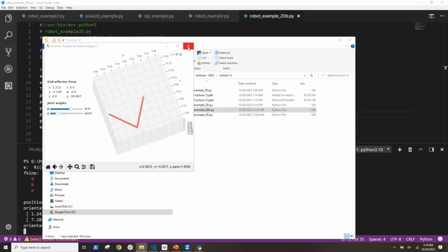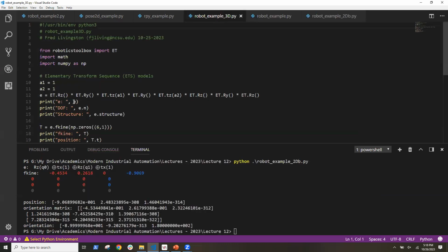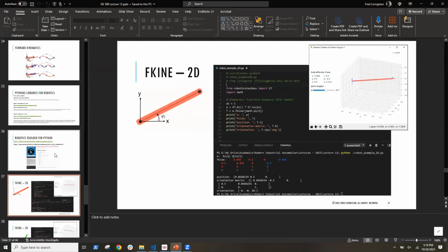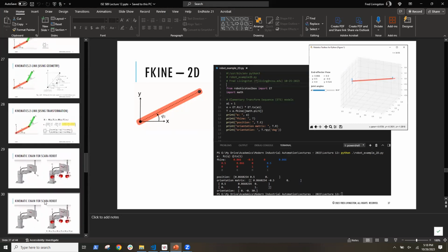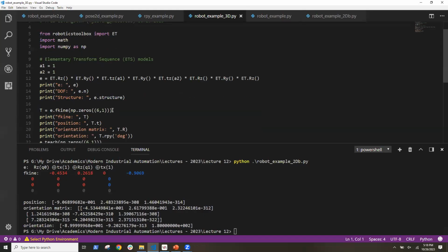Let's just move up to a higher order, and so let's go to a 3-dimensional drawing here. And so now I am doing rotations in Z, but I'm also doing rotations in Y. So I want to get out of the board now. And so I'm just adding. So this would be more like that SCARA robot. So I figure out the right transformation for that particular robot here. So something like this. Once you have that, you could just put it in here and you could confirm to make sure that it matches by simulating and then go back and forth.